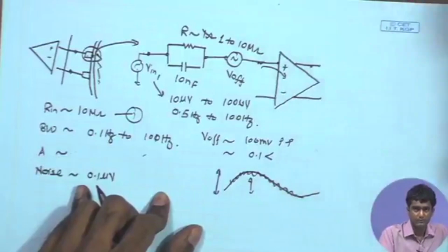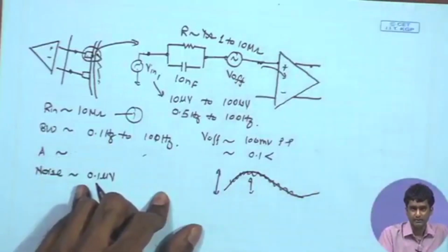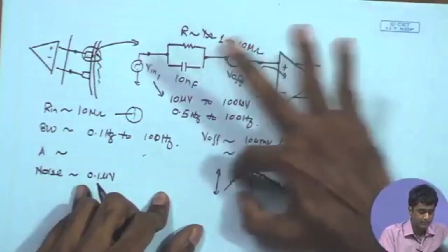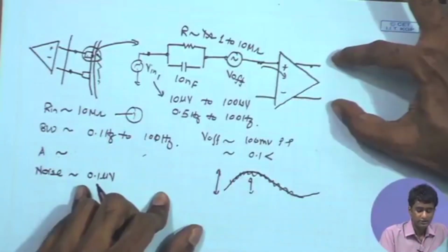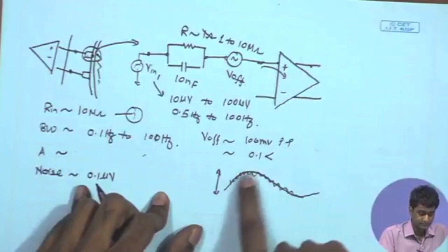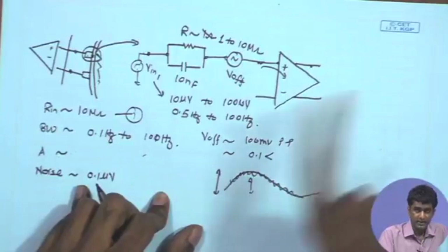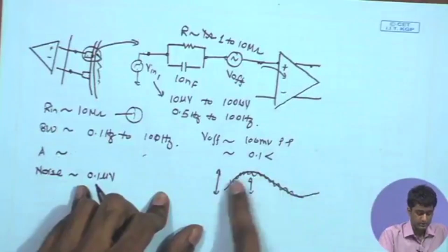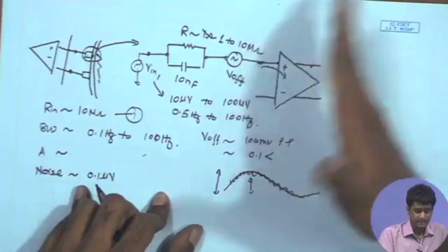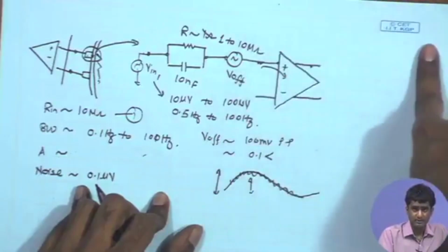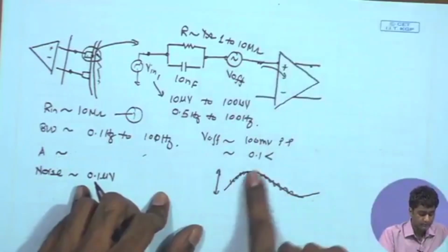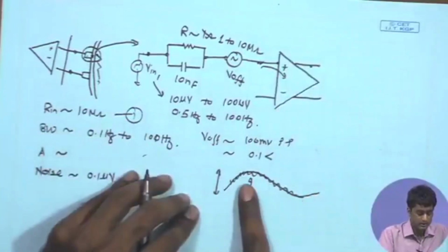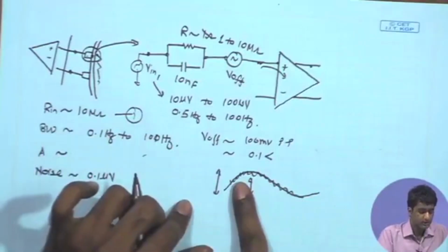So, that is one possible way that we can think at the highest level, that you amplify both the signal a little bit, and after that you apply a filter which is going to be a very sharp cutoff frequency filter, and as a result you reject the slowly varying signal and then pass on the remaining desired signal, and in subsequent stages you can keep on filtering further. But in general that is not a very standard way of doing it, and that may not be a very efficient way of doing it.